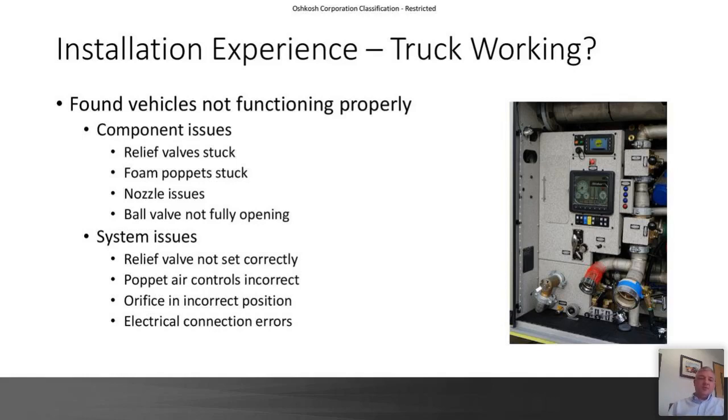Another thing with the Eco EFP system is that as you do a test, it'll show you that foam or solution flow rate. So if you have a nozzle issue and it's a 1250 roof turret and your Eco EFP system is saying that you have 1000 GPM, you're not flowing right. So is it a nozzle issue? Is it a ball valve issue? It'll help you troubleshoot those things, just outside of giving your foam percentage.